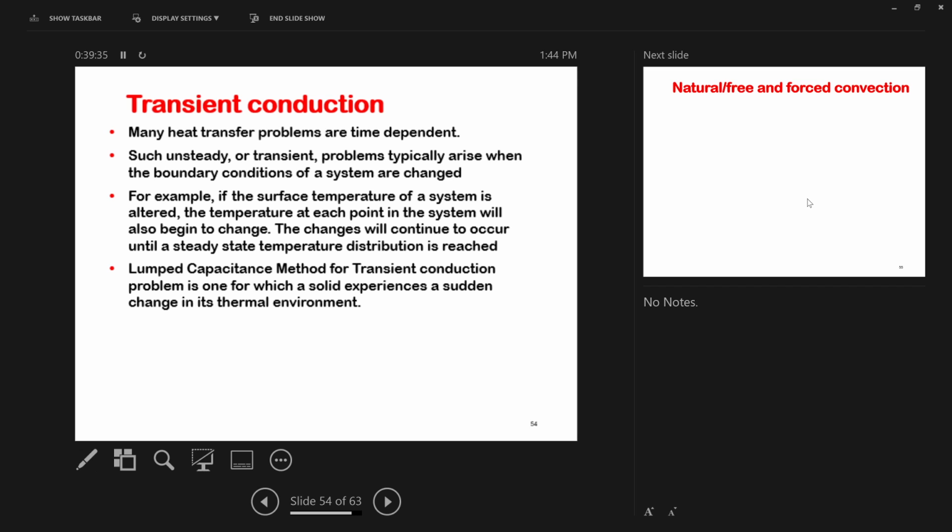These two temperatures are different, right? So you will see heat transfer inside the ball. But the first parts of the ball that are going to be affected are the near surface parts, right? The near surface part will have a temperature that is not equal to T infinity. Let's say T infinity is larger than Ts, so essentially you are heating the ball. So these temperatures are smaller than T infinity, but still larger than Ts, right?